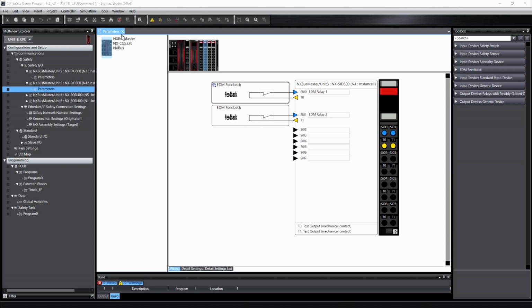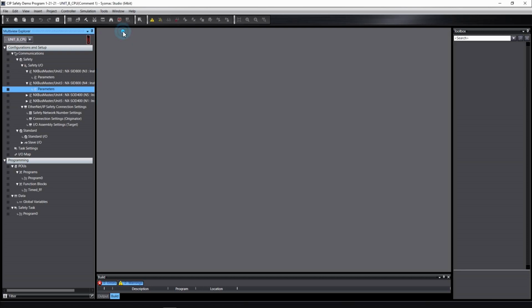For instance, let's say an e-stop or a safety gate switch in Zone 2 trips. All you need to think about is how should each of your safety outputs respond, so it turns all of your safety programming into just generating truth tables.